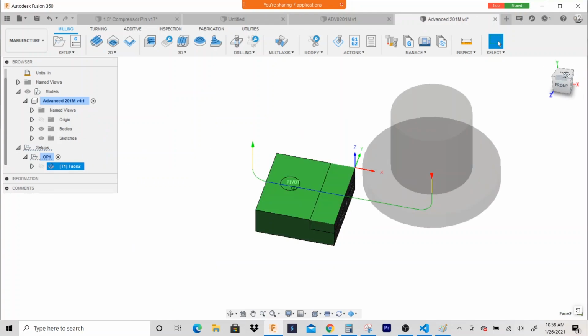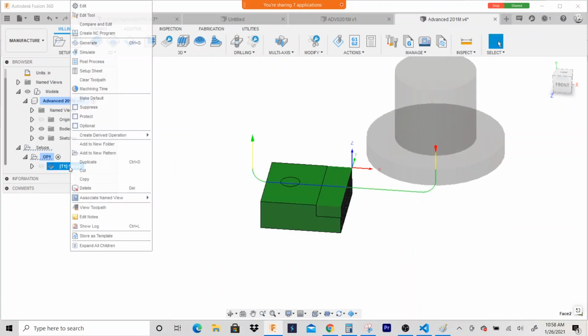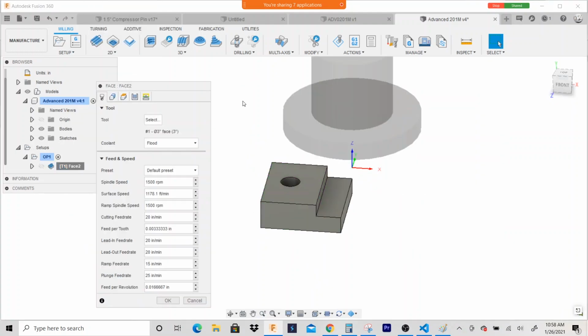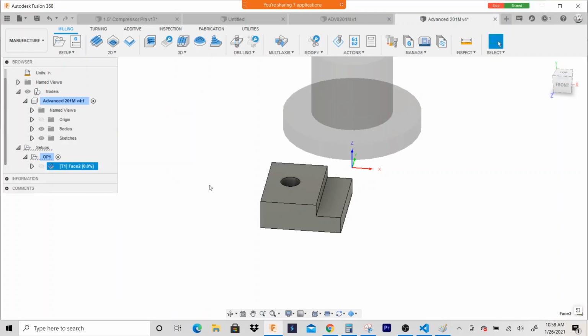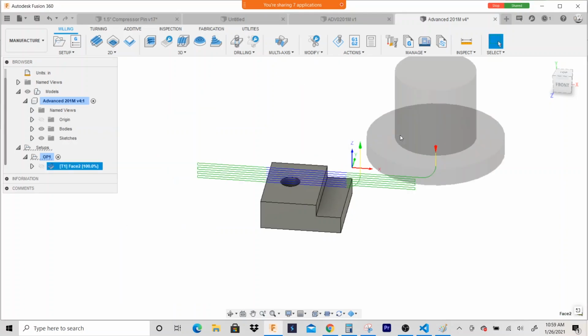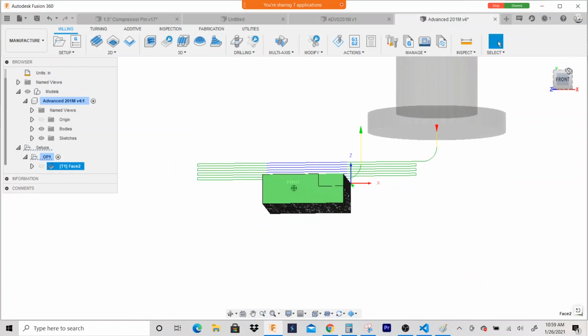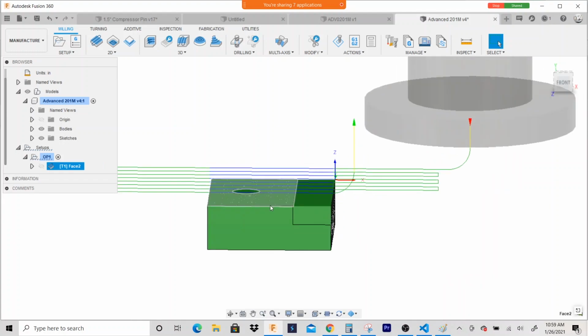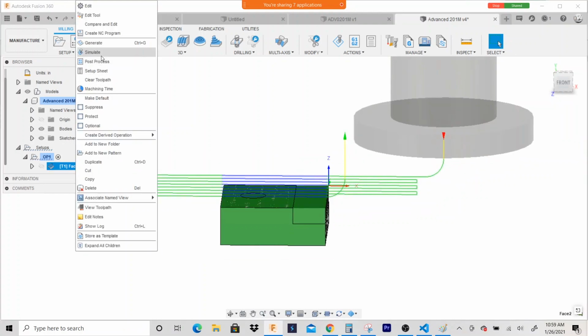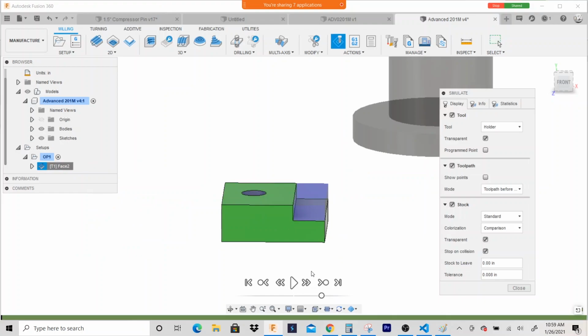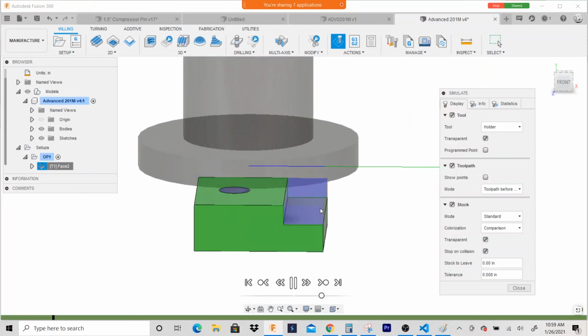Okay, so that's taking it in one pass. You probably want to take it in a few passes. I'll go multiple depths. Let's do 0.05. So I have something like this. This is assuming that the material is tall, that you're going to saw a piece that's 1". So it looks something like this.